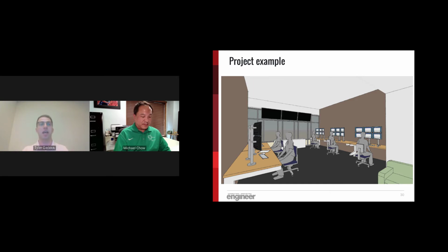So the people on the camera are not going to have light on their faces. And then the other problem is the aspect ratio of brightness from the monitors versus darkness on the wall behind. So the people working in these spaces are going to have severe eye fatigue by the time their shift is over. And the IES does have recommendations on what that contrast ratio should be, but in general, dark walls behind bright monitors are going to throw that out of balance, and the eye fatigue is going to set in.